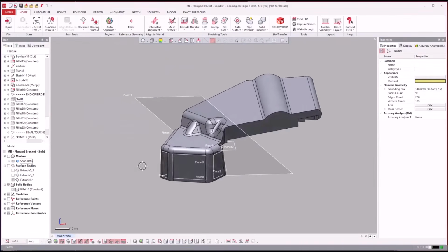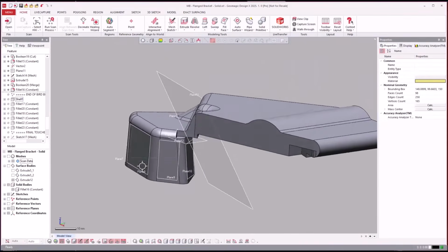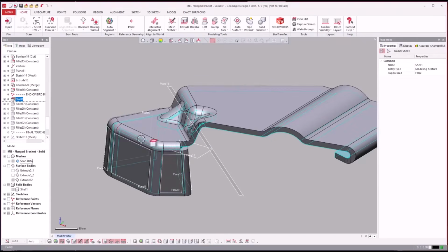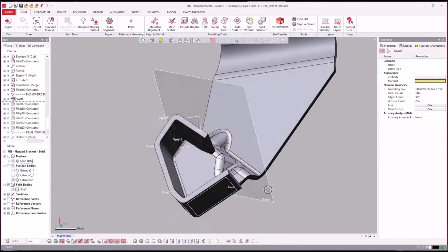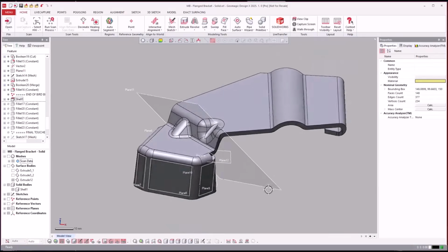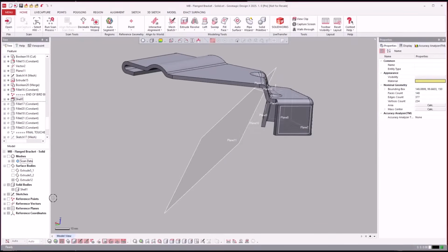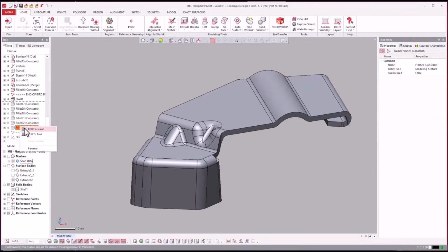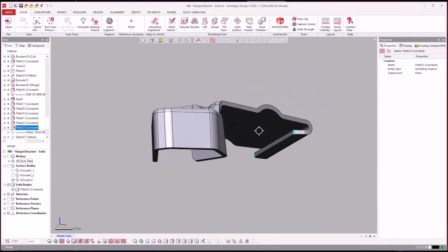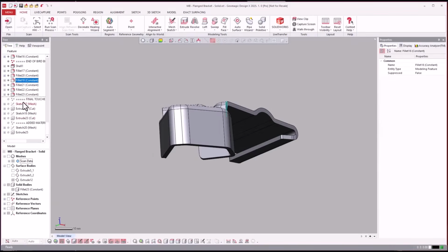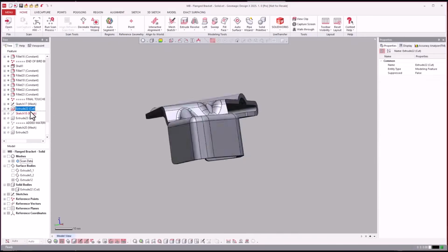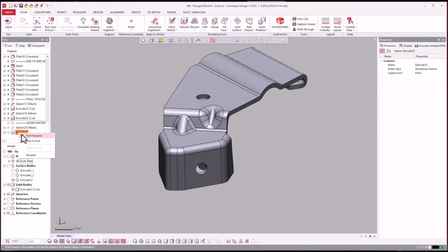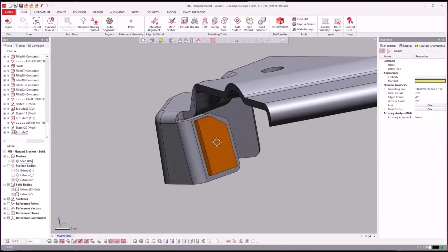So you see, so far what we've done is we've just modeled the entire top of the stamped out sheet metal part. Now we're going to say shell it. So we shelled it and got rid of all those back and side faces, and we now have a constant thickness part. Now from here, it's just dress up pieces. So add fillets, a bunch of these little dress up pieces there. Cutting our holes away from the side top there, and then adding this little piece there.